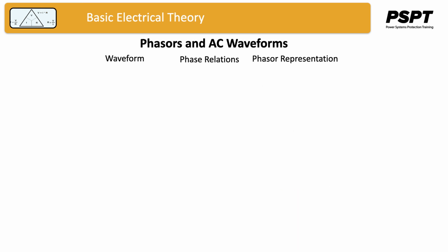Before progressing further, we'll establish that all the sinusoidal wave phasors, voltages and currents, rotate at the same frequency. In the North American standard, the frequency of the system is 60 hertz or 60 cycles per second. So all the phasors, currents and voltages are all rotating at this frequency. Hence, they are separated only by a phase shift that can vary from 0 to 360 degrees. The angle of the vector, however, represents the phase shift in degrees between the waveforms in question and another one acting as a reference in time.